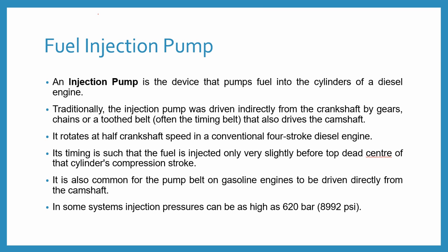So it is also common for the pump drive on the gasoline engine to be driven directly from the camshaft. In some systems, the injection pressures can be as high as 620 bar, which is near to 9000 psi.